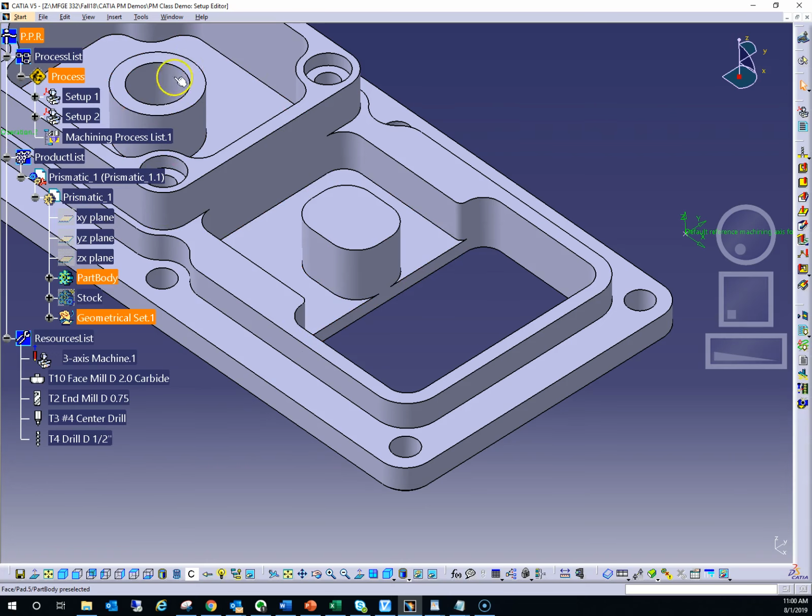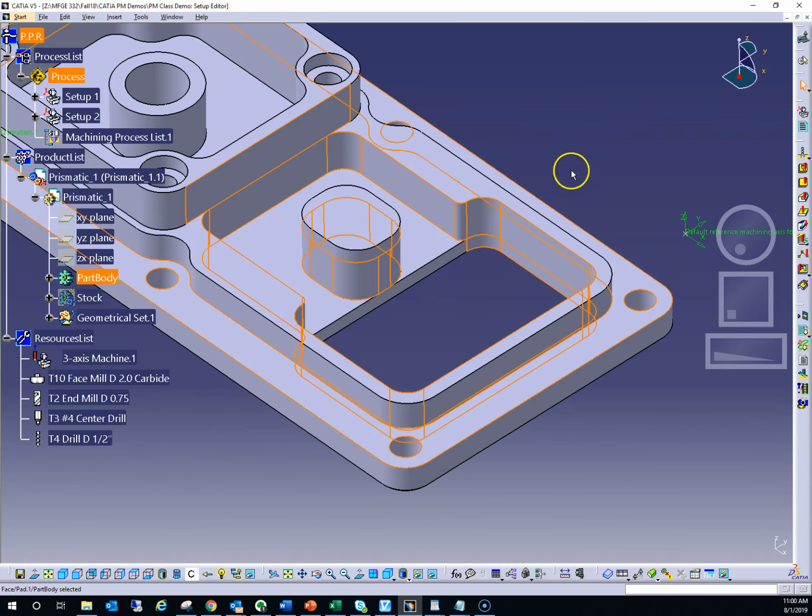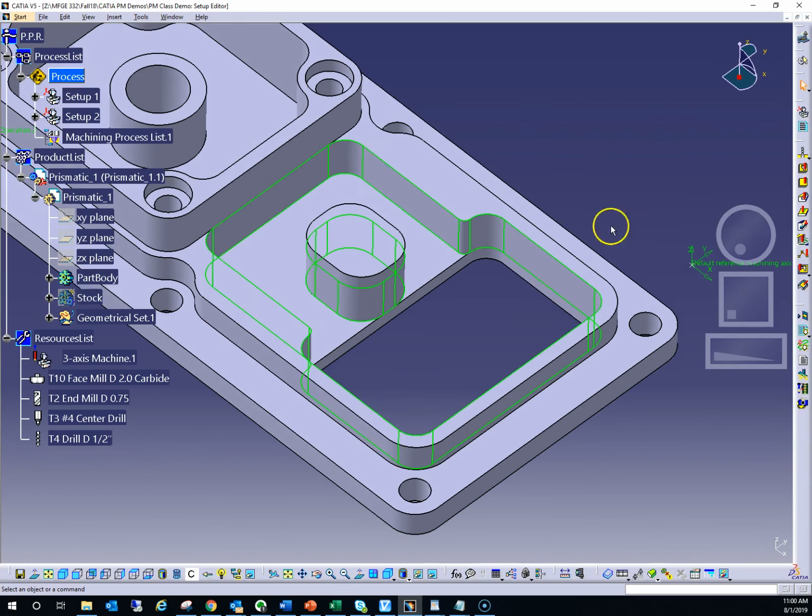over here. So if we machine the first pocket, that needs to take into account the island. So that would look something like this. So we would use pretty much all of these walls as the boundary of the pocket. So this would be a closed pocket, but there's an island in here that we have to avoid as we do that machining. And then finally, we have this open